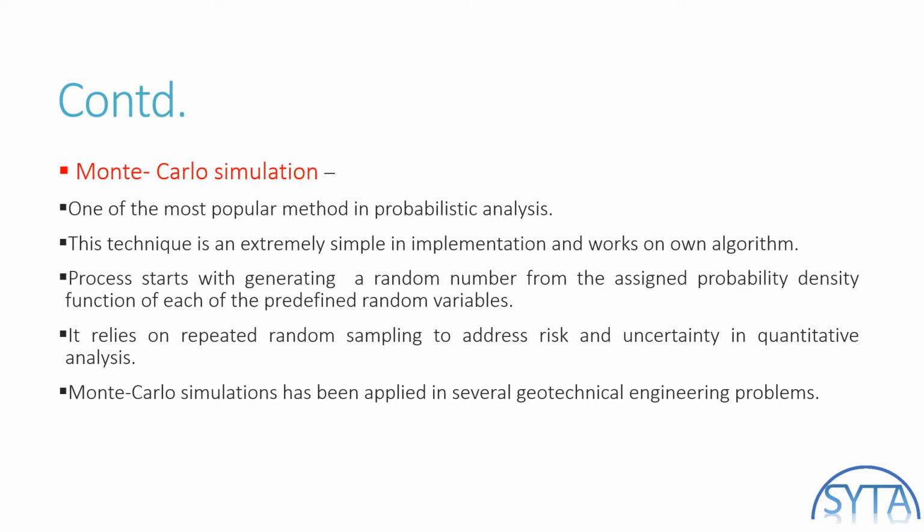That is, for example, we can assign a certain range of values to any variable, like for example the Young's modulus or the angle of internal friction or any other randomly changing input parameter. And we can see the sensitivity of those variables on the results that we get out of the analysis,